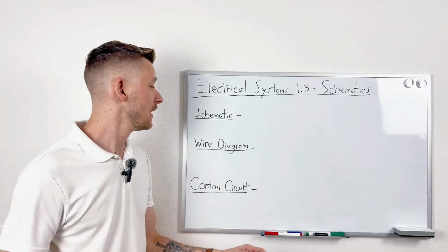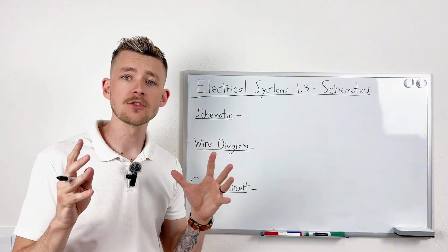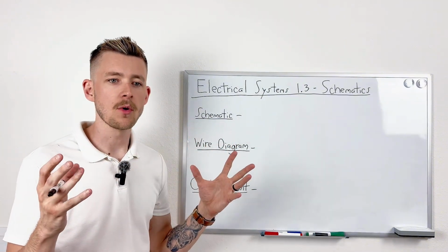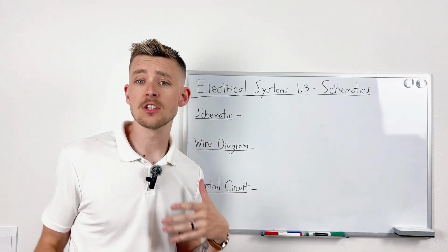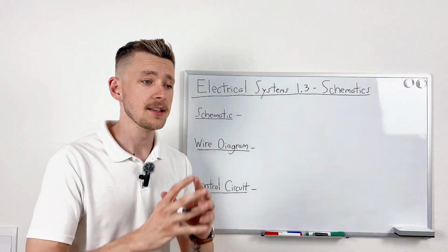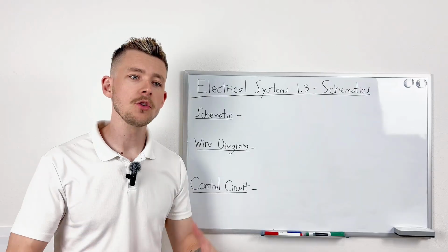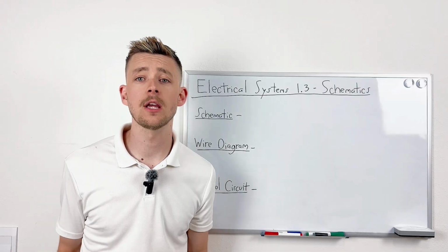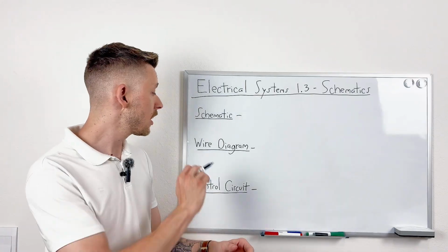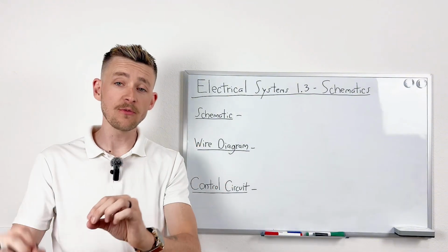So when it comes to a schematic, this is basically going to be the overall functionality of that electrical system, right? This is going to show you the pathway when it comes to your switches, your devices, your motors, your overloads, your fuses, basically what goes from where, right? It's like an overview of the system and how it works and how things are connected, right? Whenever you look at schematics, you're looking for the theory of operations and the order in which things are performed or executed.